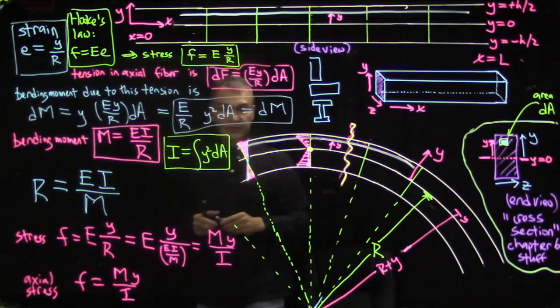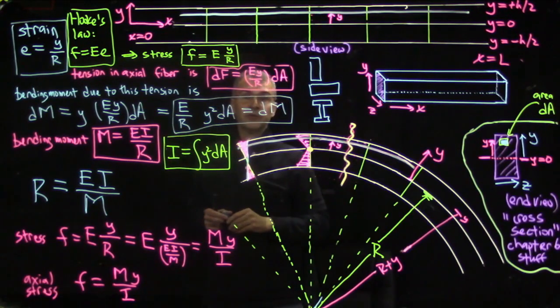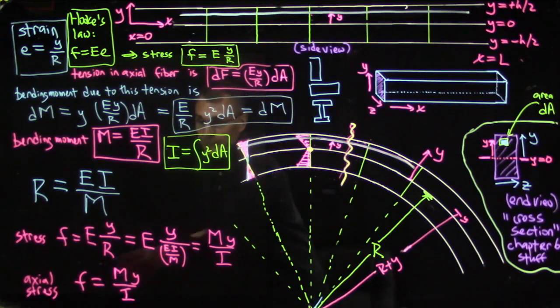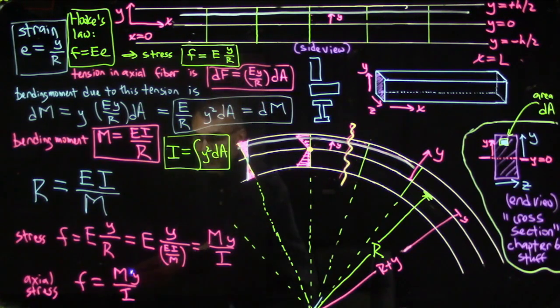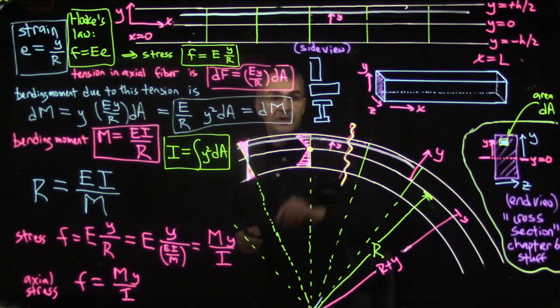It is proportional to the bending moment. So now you see why we drew those M diagrams, because the place where the internal axial forces are trying to snap the fibers of the beam apart or trying to crush the fibers of the beam like a cardboard box, those internal stresses are proportional to the bending moment. So that's why that M diagram is useful, the bending moment diagram. And then we can see that those internal stresses are biggest where we are farthest from the neutral axis. That's not surprising because we saw that the strain is biggest when we're farthest from the neutral surface, and the stress should be biggest where the strain is biggest.